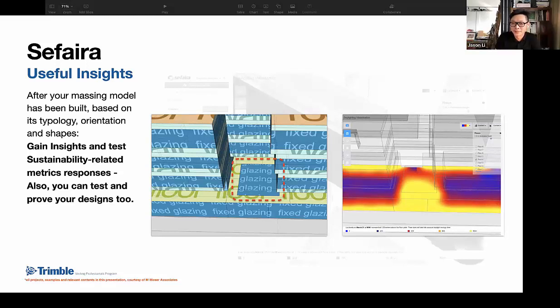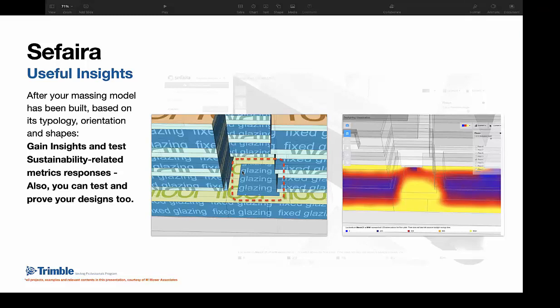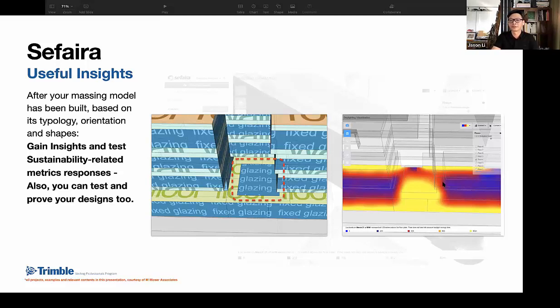You just need to build a simple architectural massing model and change the different entities into preset types, like fixed glazing or pre-built glazing, roof or slab, right? And you can get the visualization pretty fast. The most important thing, I think, is that it helps you test and try a lot of different options to find the best one.